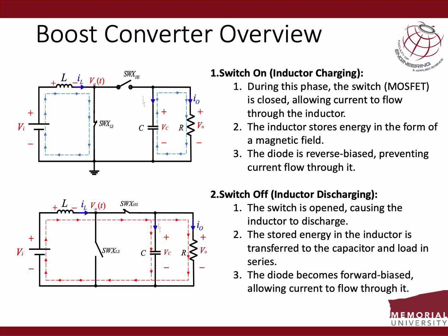Now, at the load side of the second figure, because the inductor stores energy or charges, the voltage across the capacitor plus the voltage from the inductor, which flows through the load, gives a voltage greater than the initial 12 volts that would have gone through the circuit.